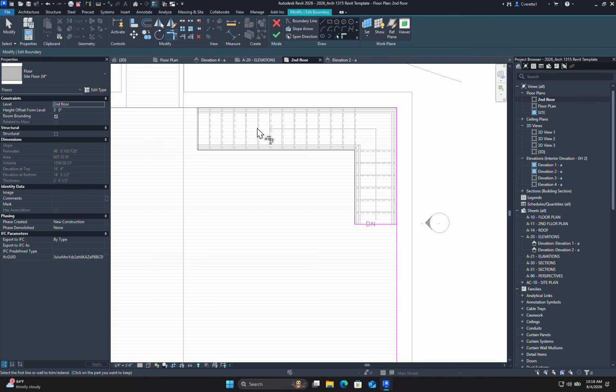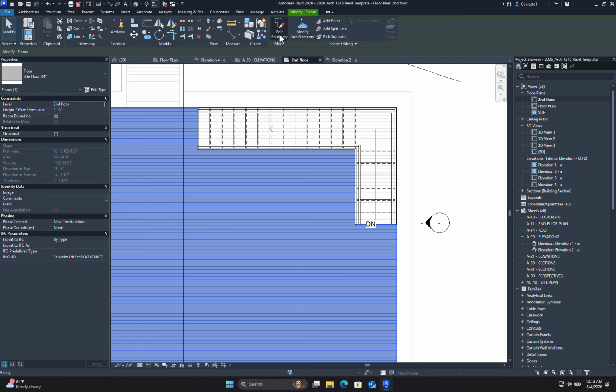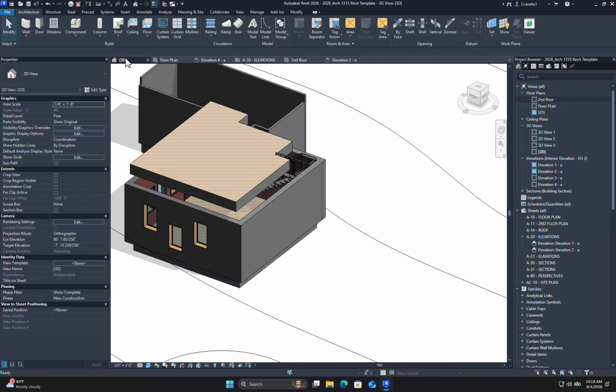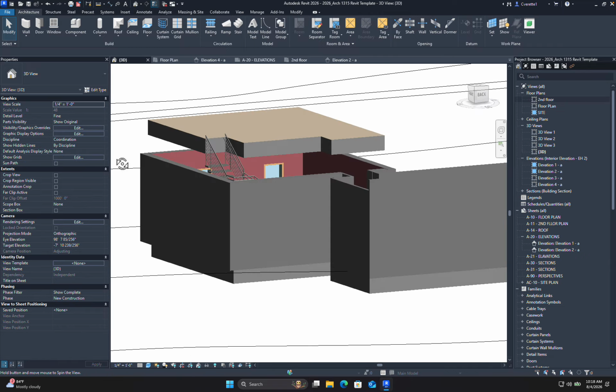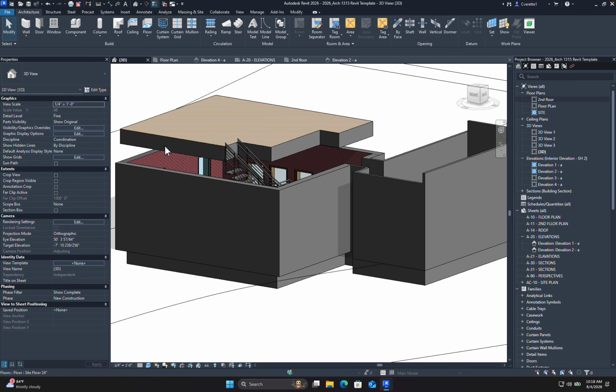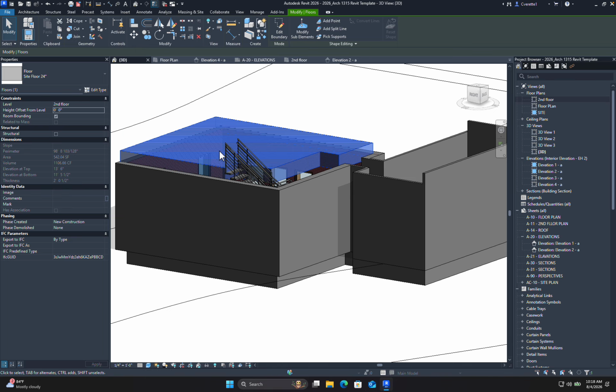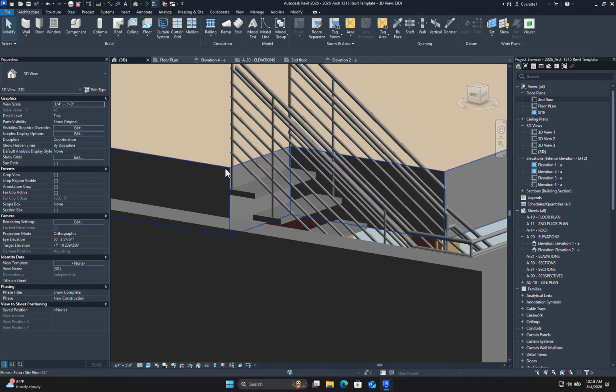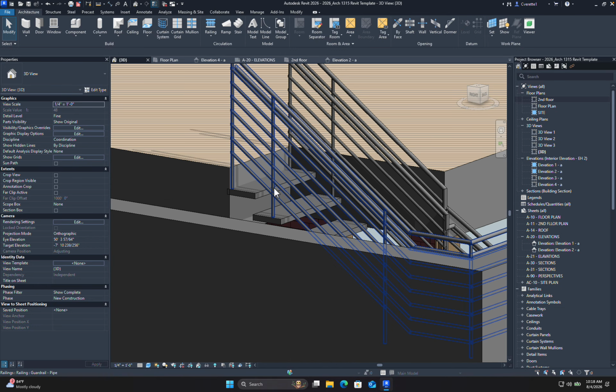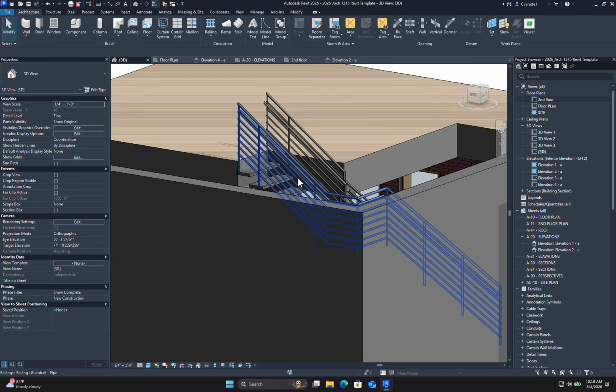So I'm going to do TR and basically make the perimeter of that piece. Now, once I hit check mark, now there's essentially a hole there. However, by default, it accidentally went to like 3 feet in the sky. That's okay. I forgot what I did to make that default that way, but I'll switch it back to 0, and we'll see that our stairs are perfect. They go to the exact step that we need.